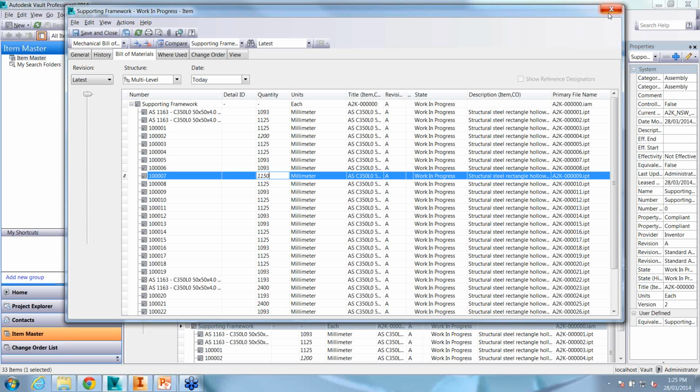So that'll always give you a 10% greater runout. As well, if you're using cable and harness for cables, you can round up cable length to the nearest meter if you like, and the same with the tube and pipe environment within Inventor. So it depends kind of on the CAD application really. The only way in Vault to do it would be manually changing it in the bill of materials that I just showed you. Okay, I hope that answered that question, and I'll give it another minute or so